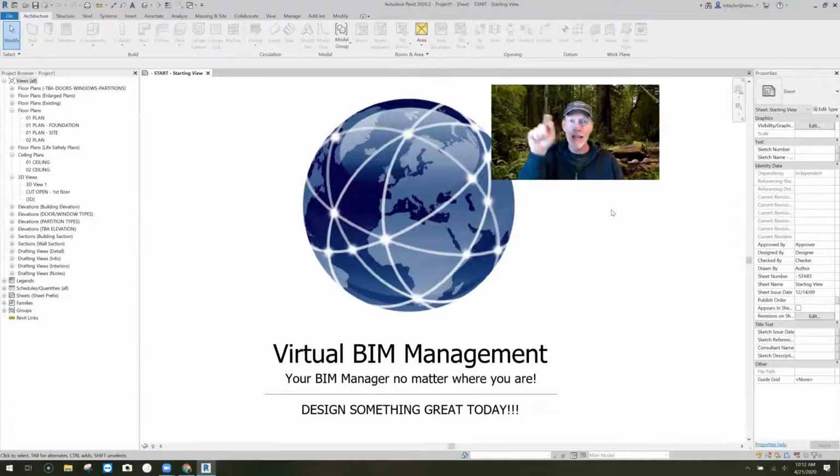You can have wavy line patterns. You can make speckly dot patterns. You can make any brick size patterns, CMU patterns, economy brick patterns. I have done so many different patterns for the clients. Like interior designers are always asking for new patterns, because they have different carpeting patterns, they have different wood patterns, and the program Hatch Kit will create a hatch pattern, which has an extension of PAT. And then you import those into Revit. I'm going to show you how to do that really fast.